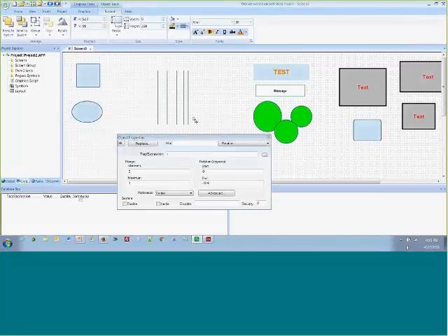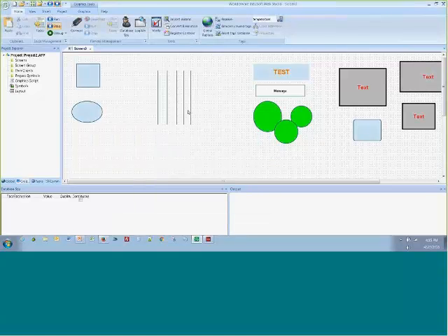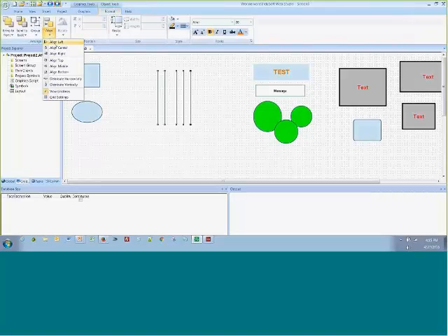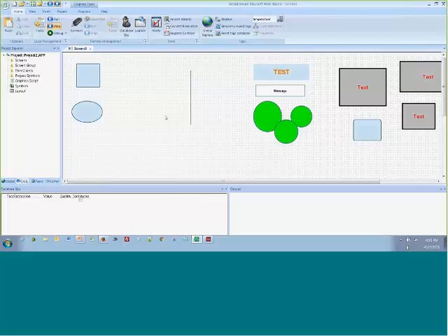And then the next one will make positive 22 degrees rotated. And I could do further more of these to get the complete scale, but you'll get the idea of what this does. And now what I'm going to do is stack these on top of each other. And rather than doing this manually, because sometimes with really thin lines it's hard to do, I'm going to window around all of those objects, select them all, and then use the format align center, and align middle. And now they're all stacked on top of each other.